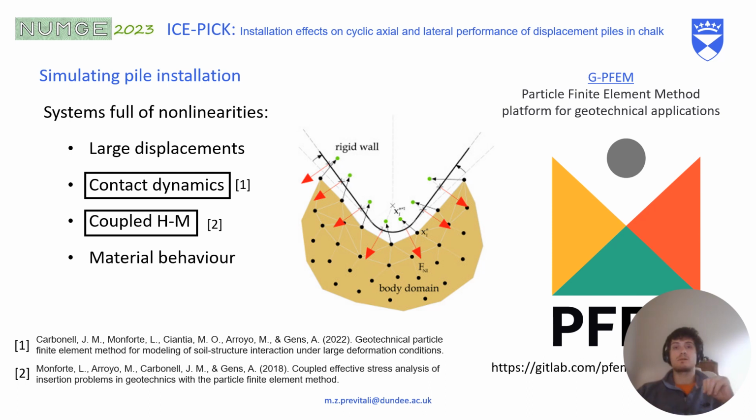Then contact dynamics and coupled mechanical behavior. I'm not going into details, but we are using GPFEM, which is an open source platform especially developed to solve geotechnical problems. In this platform, the problems of contact dynamics and coupled hydromechanical behavior have already been solved by other people, as shown in the reference there.